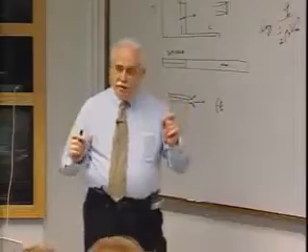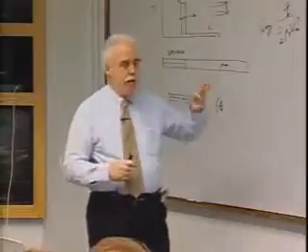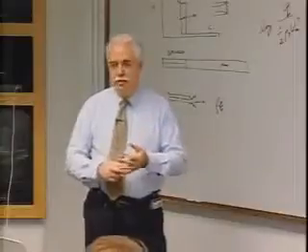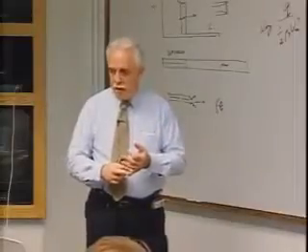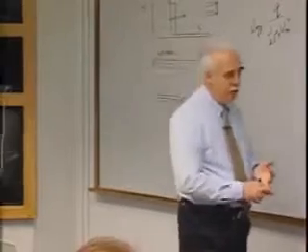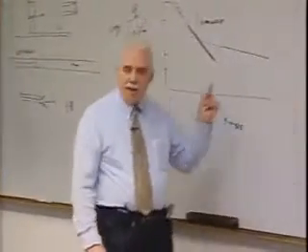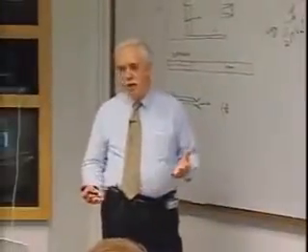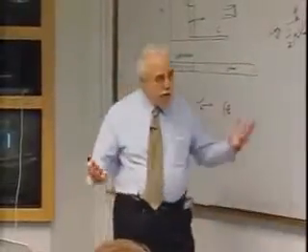It is very valuable information, but you really need to understand what you're doing with that. You can't just take Mach number as the major parameter. It is a significant parameter, but you need to get the Reynolds number, and fundamentally you need to get the enthalpy of the gas. And there's not really a good dimensionless number for the enthalpy of the gas. Okay. Too much going on for that.